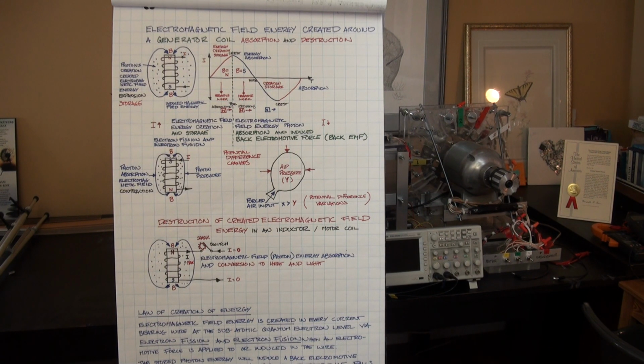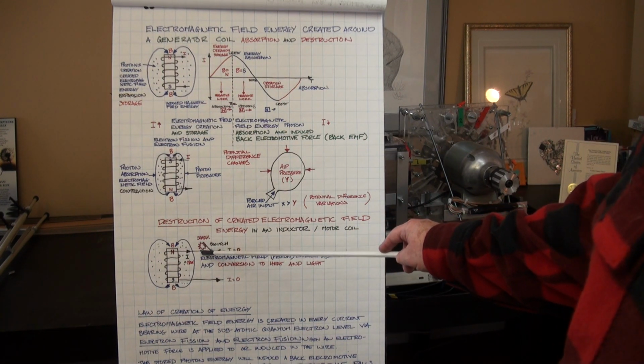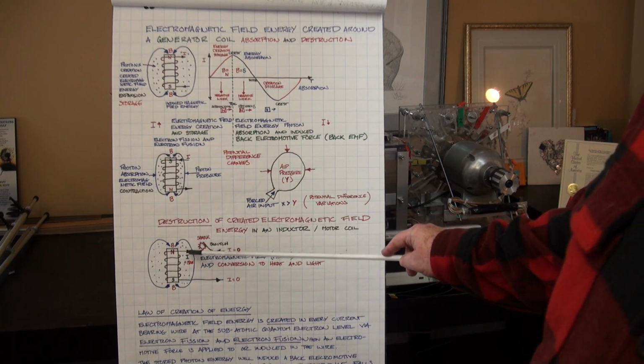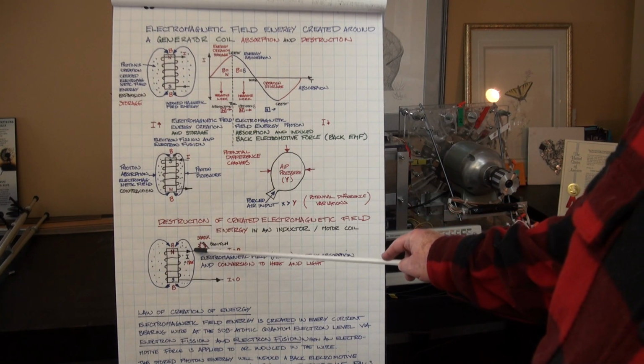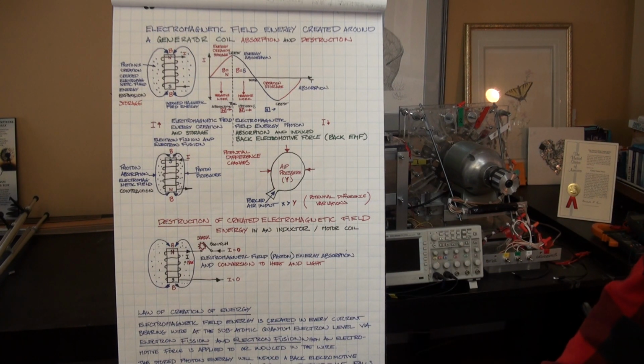And anybody that has ever seen the operation of a brushed motor will notice that the brushed motor produces sparks. The spark in a brushed motor is the instantaneous opening or disconnection of the applied voltage to the motor coil.